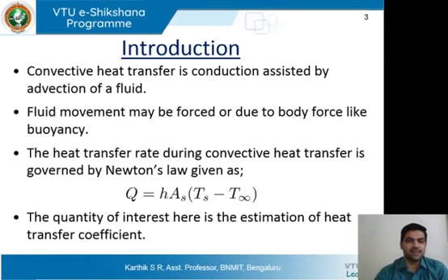Conduction is predominantly a molecular phenomenon, which relies on diffusion of energy at a molecular level. Convective heat transfer is simply conduction which is assisted by advection